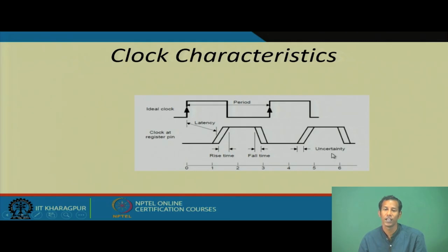So, you have to set the uncertainty on the clock period, because in real time you will face this uncertainty, and this is the real time clock which will work inside your chip. That is why you have to consider this uncertainty value while you are defining your clock.